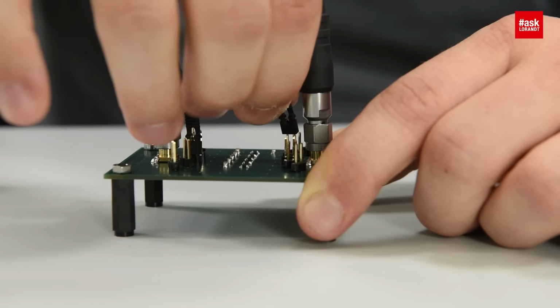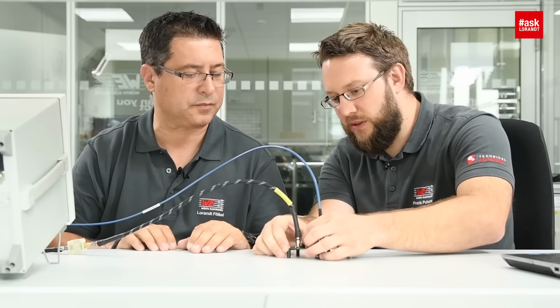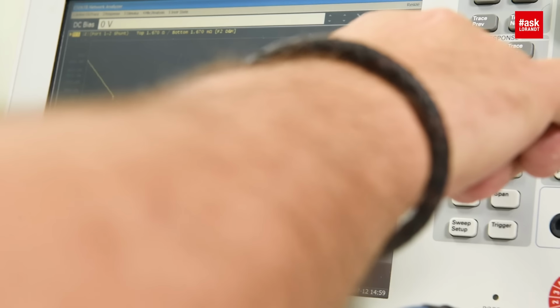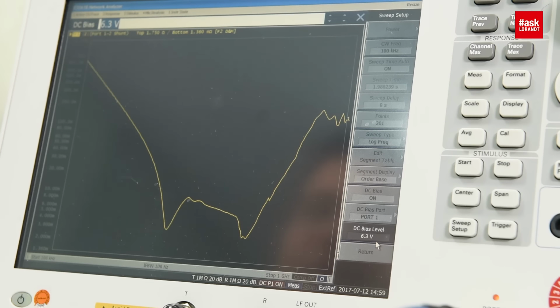The next one is an X7R ceramic with 6.3 volt to show the difference between those two kinds of ceramics. Here we can also go up to 6.3 volt. And here also no real change in the characteristics. Extremely small. So we can go up to the rated voltage with the filter. If it's an X7R, it's no problem.